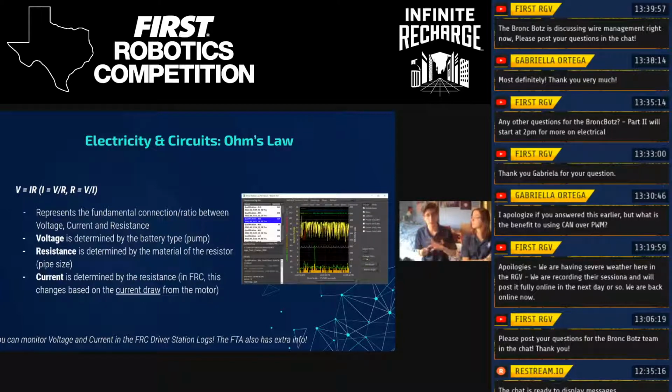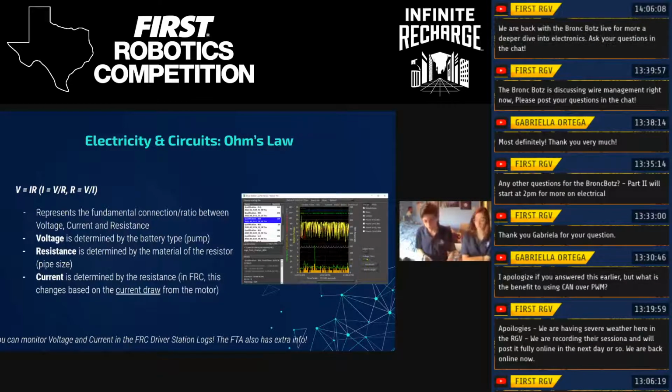And resistance is also measured in a unit called ohms, represented by the Greek omega symbol. I forgot to put that up on the slide. But basically, Ohm's law represents the fundamental connection and ratio between voltage, current, and resistance. So it's V equals IR, and then if you know algebra, you can sub it for those other equations up there.